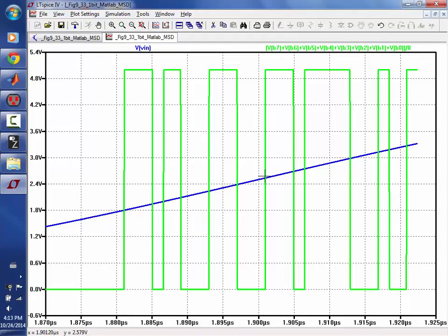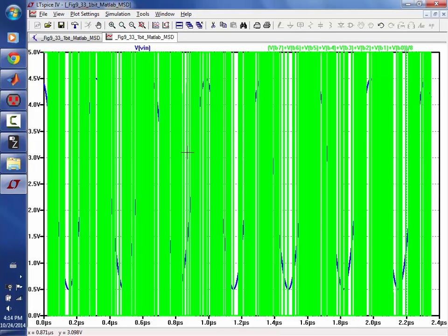The D flip-flop would go to this 2.5 volt state and sit there, and I'm like, what the hell's going on here? I played around with it for a while, and I'm like, oh, this is some issue with interfacing real transistors with ideal components, because you're not getting fast edges like you get with ideal components, you're getting slow edges. It's not working out. So we'll see what happens.